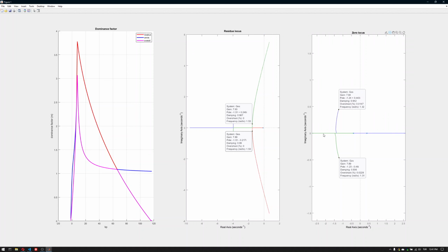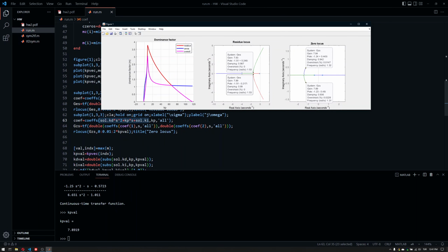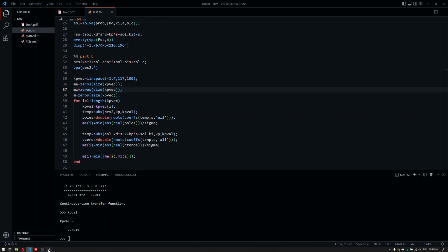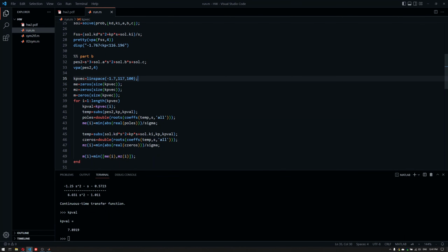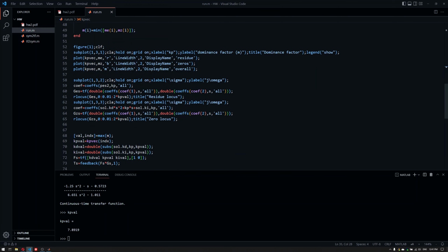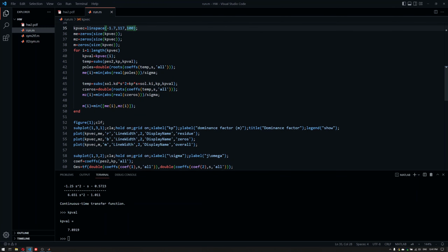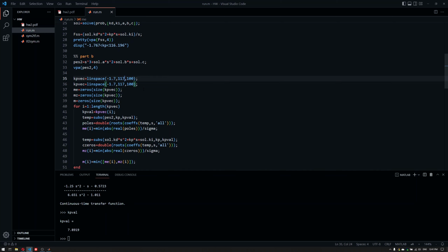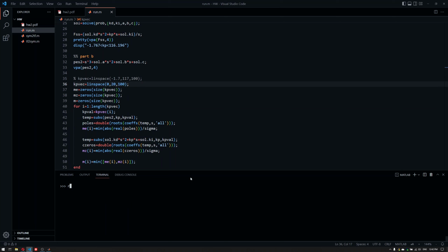Of course, there's a little numerical stuff going on, or it is about the step size that we take, because if you look close, I have chosen 100. This is not the ideal thing. Since we know that it is approximately 10, in order to increase the accuracy here, we can just go ahead and drop this down to, let's say, 20. We know that we are not using the negative root locus here, so let me basically make a copy of it. So change the interval to 20, change this to 0, and then run everything back again to get a better result.